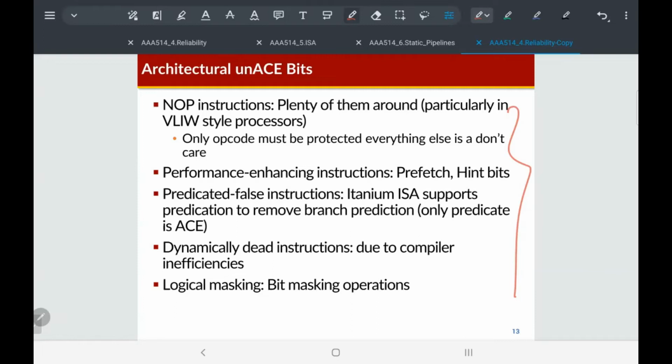Also, another issue is refresh in DRAM. Refresh is also very critical because the electric charges in the DRAM capacitor dissipate over time. In order to recover these dissipated charges in the DRAM capacitors, we need to apply refresh. But refresh is also critical for the performance of DRAM because during the refresh period, we cannot use these DRAM devices. So refresh is also related to the reliability issues.